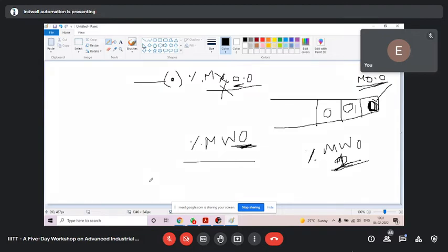As the timer starts and finishes 2 seconds, as 2 comes in %MW0, 10, it means the M1 flag will be high and the M0 flag will be off by itself. You will be wondering, what's going on in my program, why are the coils turning on and off by themselves, I'm not operating them. So this is the effect of word on bit. If you are using a bit, don't use its word. If you use a word, don't use its bit.